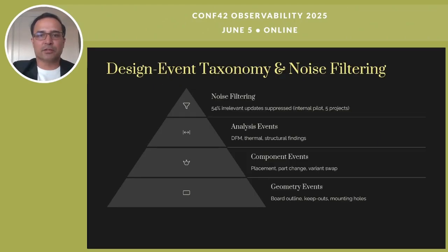Now we layer two cross-cutting enablers. Taxonomy: geometry events, like board outline, keepouts, mounting holes. Component events like placement moves, part swaps. Analysis events like DFM or thermal rule results. During the pilot projects, lightweight heuristics, nothing exotic, mostly debounce and deduplication, cut irrelevant chatter by 54%. That means engineers only see the signal, not the noise.